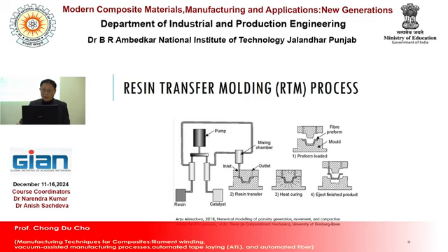So as you see, this process has the upper mold and the lower mold, and the upper mold must have an inlet for resin and an outlet. The outlet is for overflowing resin coming out during the process. And the pump is needed, and the mixing chamber, where the molten resin is, and by the pump it can be pressurized and injected into this die, this mold.